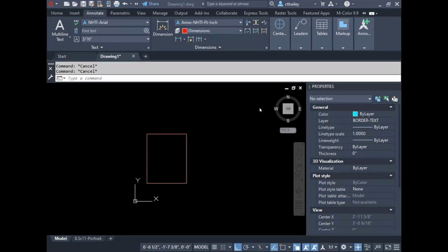On your parameter, do this with us. Yeah. On the parameter, so go back and look at it. For the parameters, bring in the base point parameter. Midpoint of your bottom line. And up, keyword. Shift right click. Okay, that's what I mean, all right. So that will go line and... Now that's the beginnings.